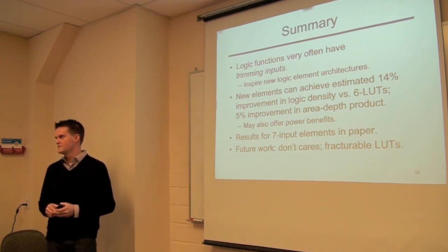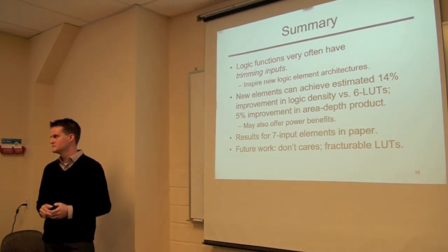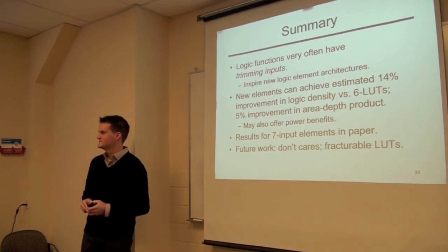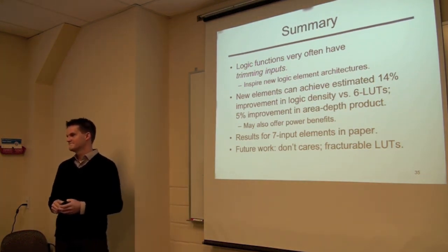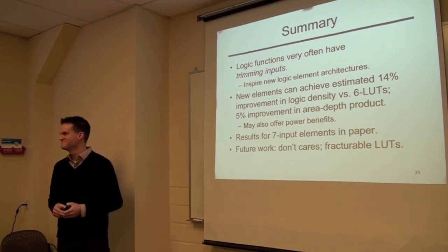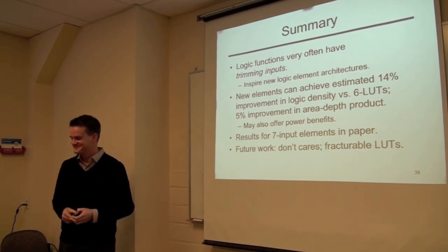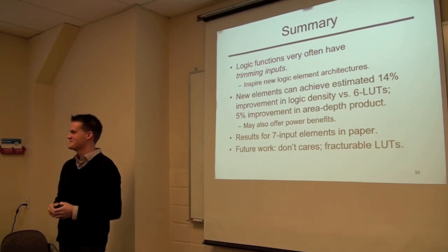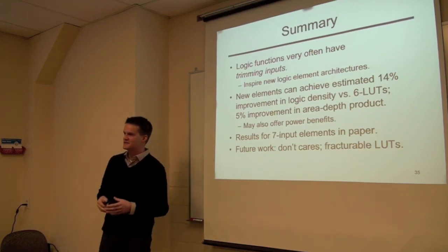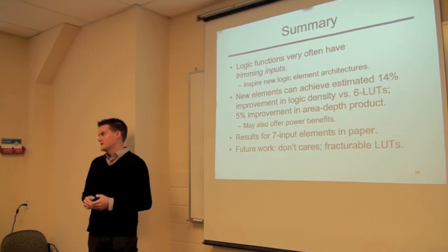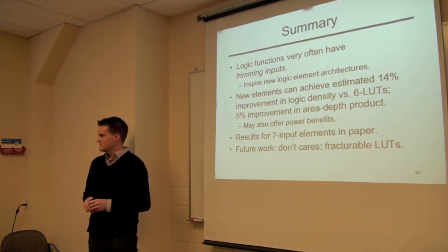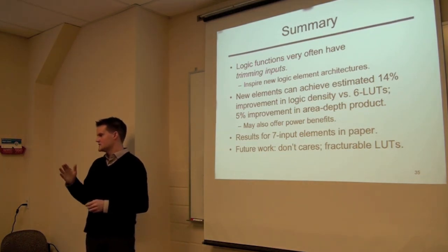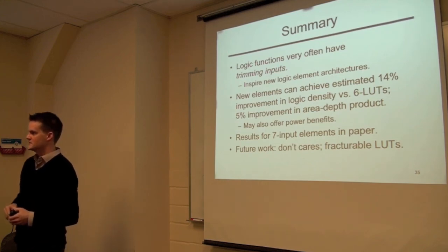Jonathan, where did you get your 25% number? It's kind of the key number that gets you your area gains. Where did that come from? Anecdotal. It strikes me as a teeny bit big. But, for 25% for the LUT RAM, I don't know if anyone... It's not just the LUT RAM. Also, the size of the multiplexer is reduced, right? So it's the whole LUT, and the size of the multiplexer is reduced in the same proportion as the number of SRAM cells.